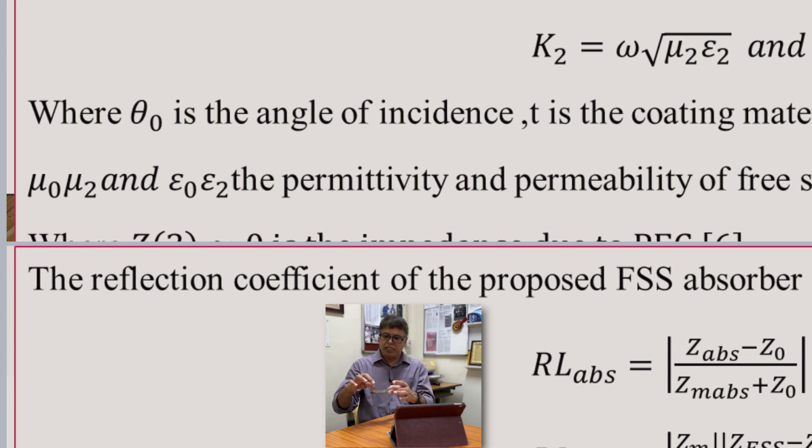Now these are metamaterial absorbers. The reason being, the structure is specifically designed so that the incident wave phase angle is changed by these structures. Or we can say that in place of reflections, the waves are routed towards the substrate, and they travel to and fro, in both ways. The EM waves travel inside the dielectric, and the travel movement will constitute a dielectric loss. So this is all about the RF absorber. Now this S11 as well as the absorption parameter can be measured with the help of a vector network analyzer.